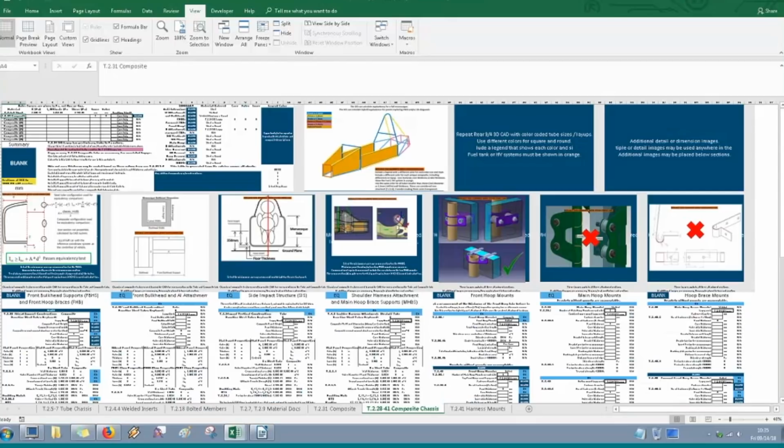And a quick note on hybrid cars: if your team's looking to do some simple composite panels, the SES is set up to do hybrid equivalents on the front bulkhead support diagonal or the side impact diagonal. So those are two simple panels where you can use the SES to do flat panel equivalents and put them into a tube frame.